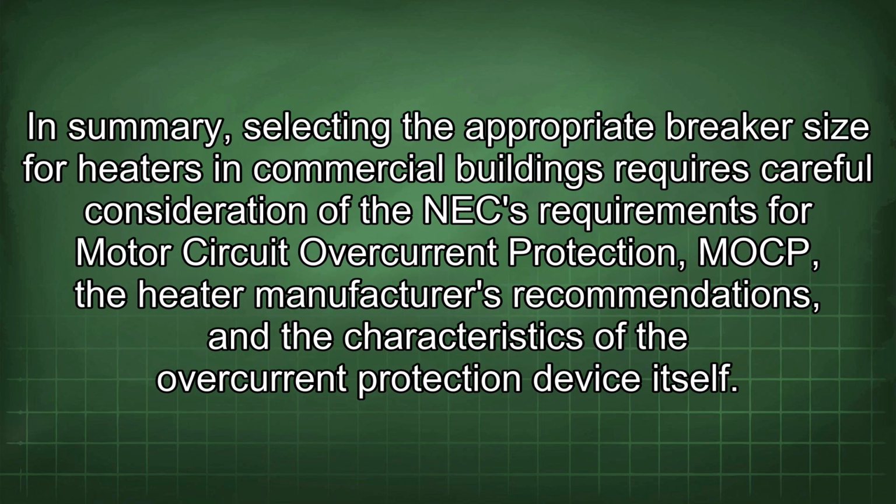In summary, selecting the appropriate breaker size for heaters in commercial buildings requires careful consideration of the NEC requirements for motor circuit overcurrent protection, the heater manufacturer's recommendations, and the characteristics of the overcurrent protection device itself.